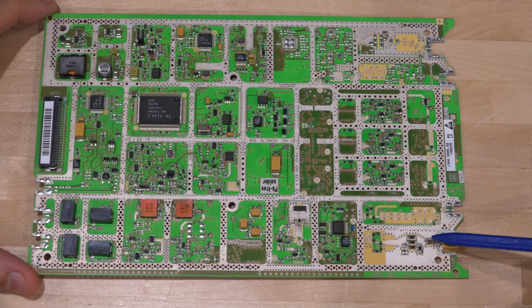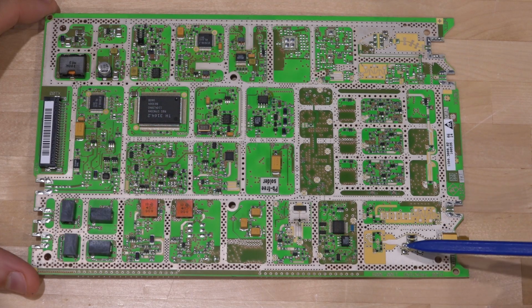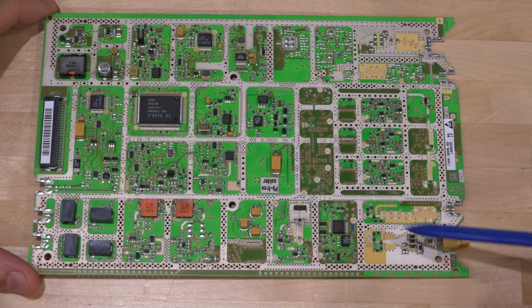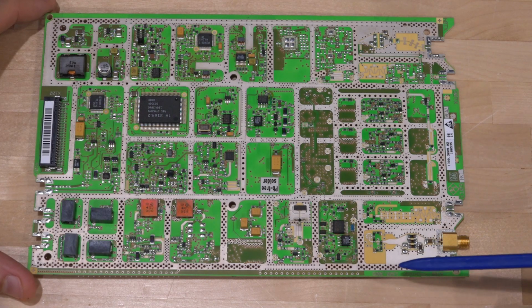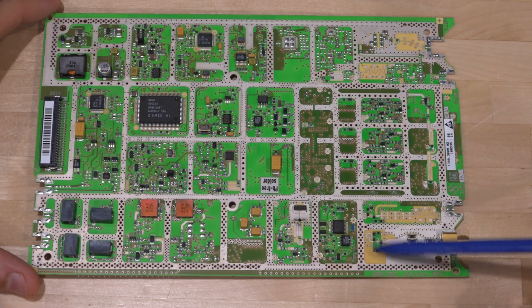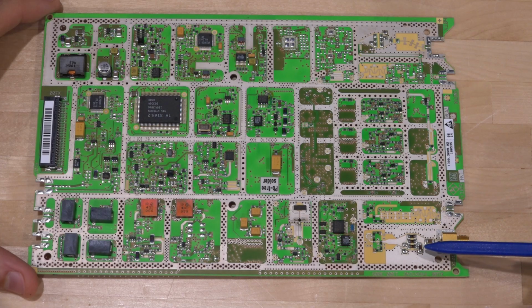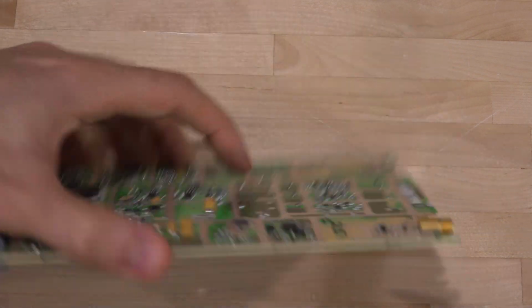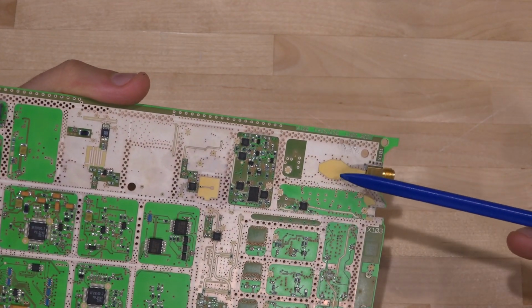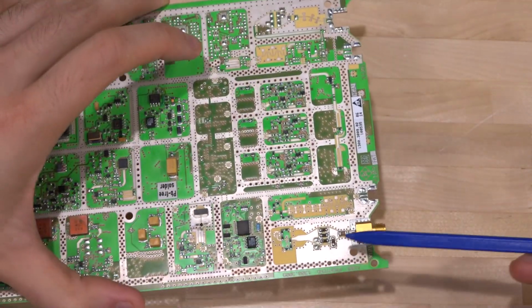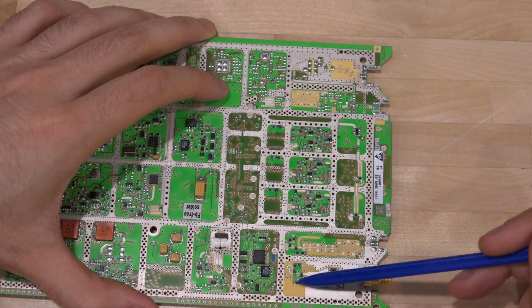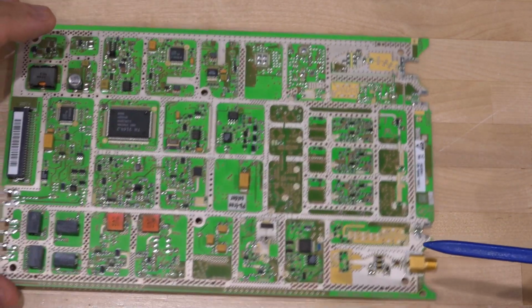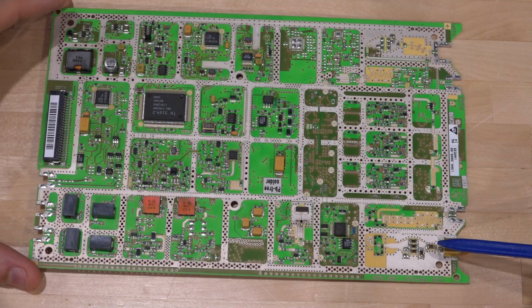So here's the RF input, here's our AC blocking cap, and some input protection over here with the diodes. This section is quite important because you want to maintain a really good characteristic impedance of 50 ohms. That's the impedance seen by whatever device under test you connected. So you want it to be as good a 50 ohms as possible. If you look on the other side, you can see they've removed the metal in order to reduce the parasitic capacitance of these components that they had to put on top. And here are the three series diodes as well. So that's probably a fairly good input.